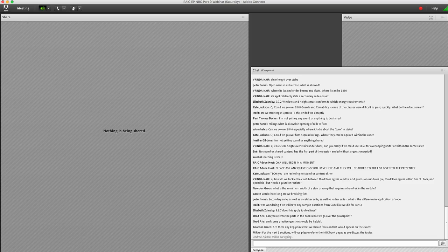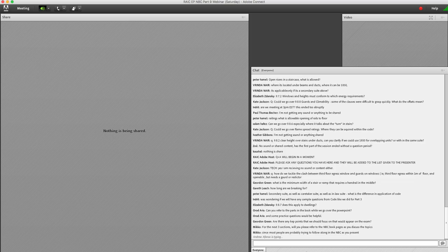Okay, another specific question I did have is the requirement for the minimum number of risers in a set of stairs. So that is related to NBC Article 9833, where it's stated that except for stairs within a dwelling unit, at least 3 risers shall be provided in all interior flights of stairs. So again, bear with me, and I will get to the next question.